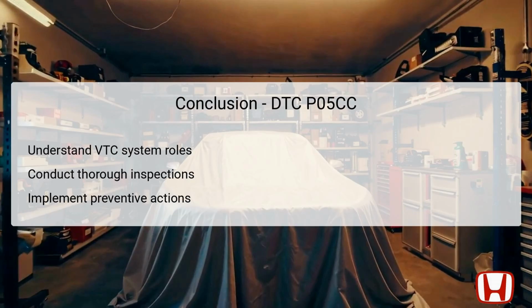In conclusion, handling DTC P05CC necessitates a comprehensive understanding of the VTC system and its direct impact on engine performance. By diagnosing the causes and symptoms effectively, technicians can systematically troubleshoot to isolate and resolve the issue. It's essential that components such as oil solenoids and passages are inspected for any signs of failure or blockage.